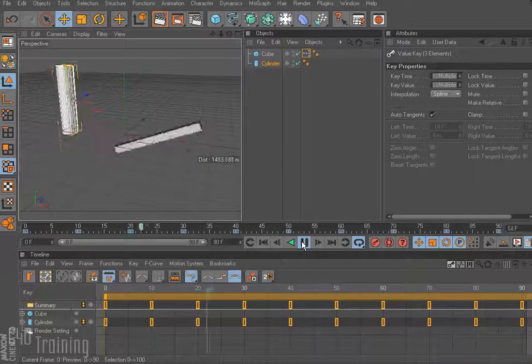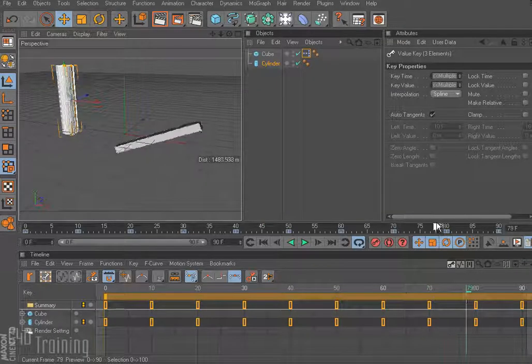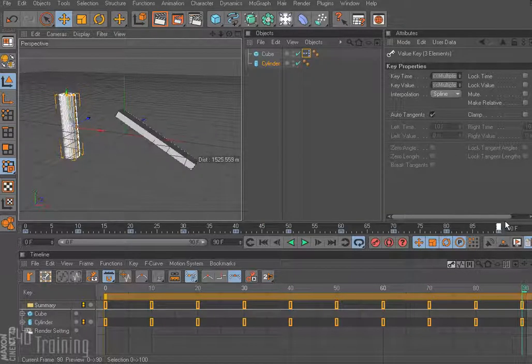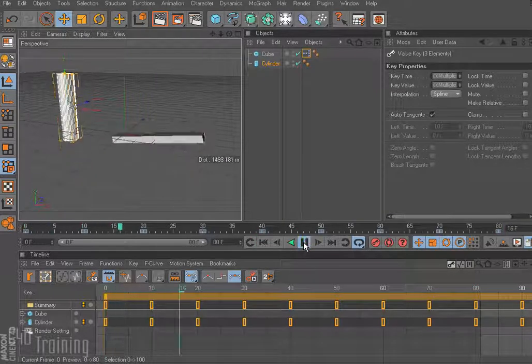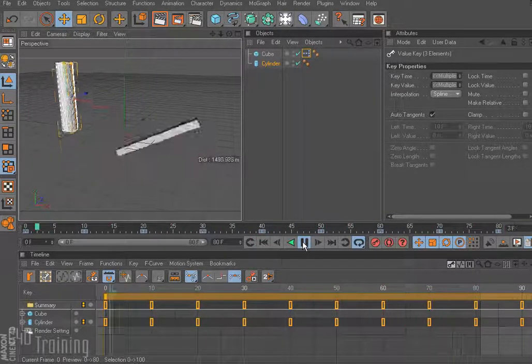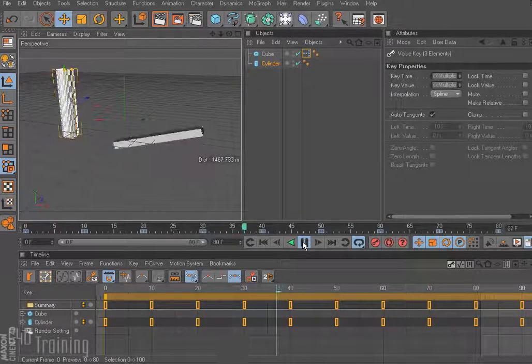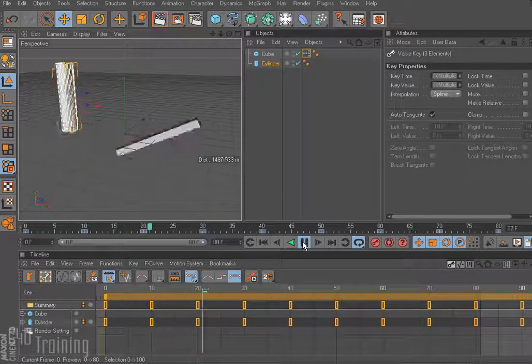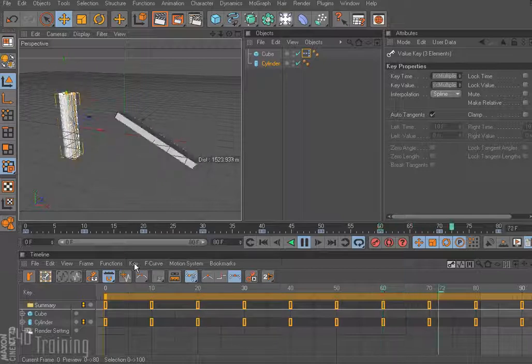So you can see it kind of glitches at the end, and that's because we go up and then we go down and then there's no up, so then it jumps back to the beginning. So we could actually reduce this from 90 to 80 keyframes, and now if we play this, it should just keep looping, and there we go. So a simple way to animate using set driver, set driven, and then in the animation window here using the key cycle.